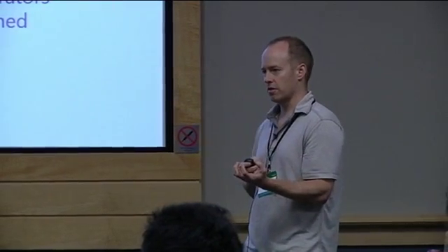So if you have a block that's very common, that you're going to be doing a lot, let's say in your phone, you're processing some sensor stream and it's in a block or two, what you can do is take that block and synthesize it into an ASIC, but have the same interface that you would have to software. And so when the software reaches that block, it can go out to the synthesized unit. And this provides you an automated way to take code regions and synthesize them into specialized accelerators.